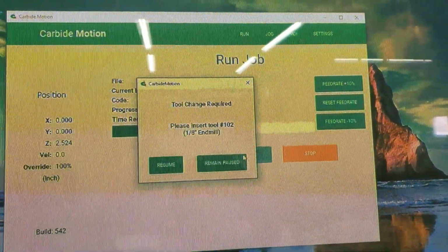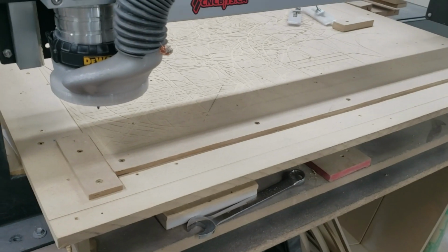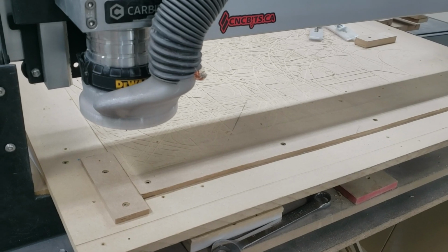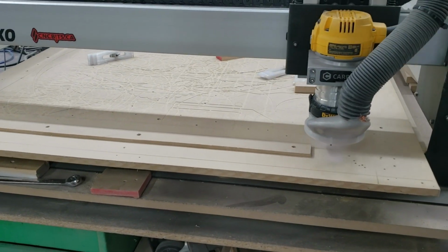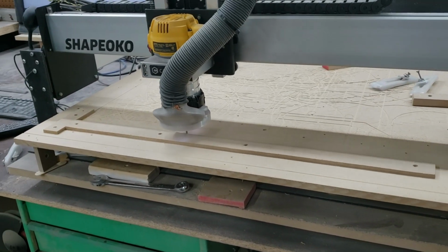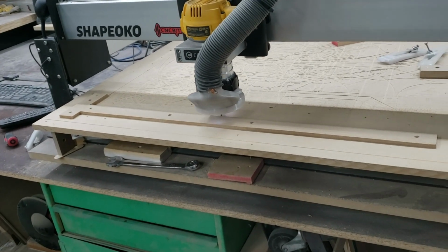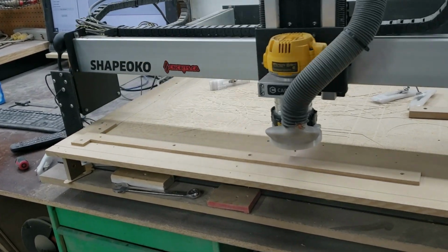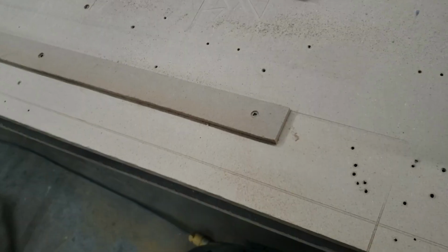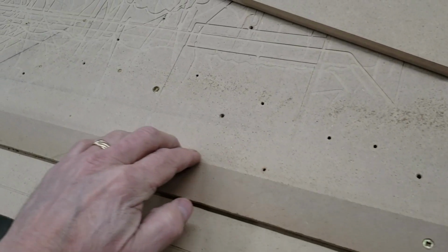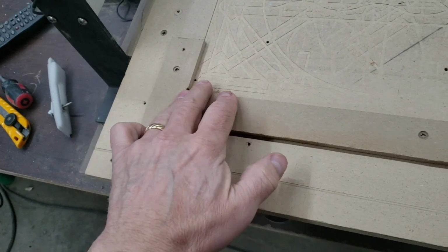Okay, everything's locked into place. Tools are set. Now I'm going to cut those 2 lines, and it's going to cut just enough into the MDF to be the absolute perimeter of my cutting area. And because this line is being cut by the machine, it is 100% true to the rails. So you know it's square.